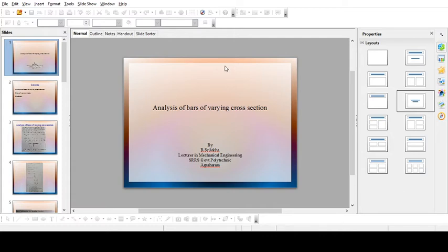It is 20 mm. So cross sectional area means, see, this is the hole. Now the remaining material you have to consider. So the remaining material is what? Nothing but pi by 4 d square minus this d square.